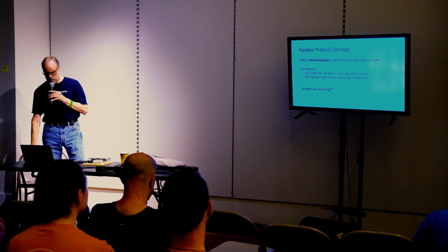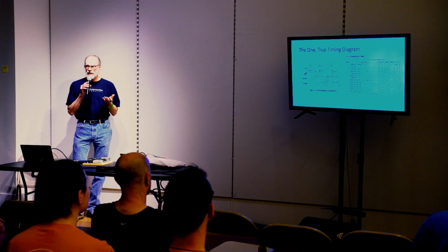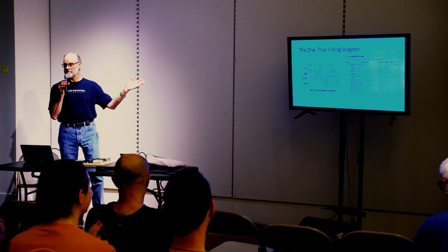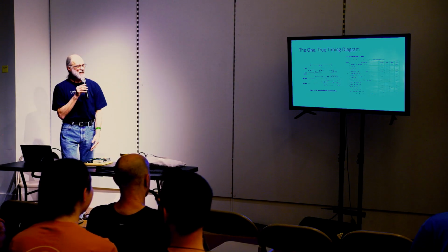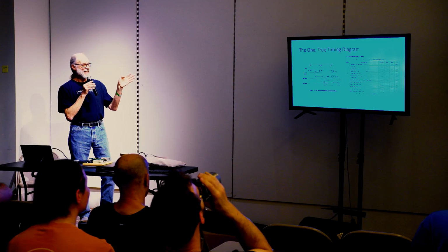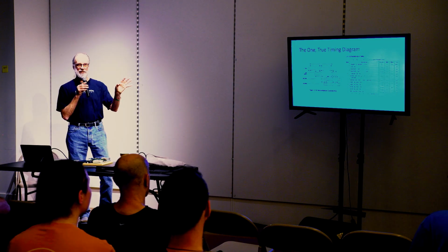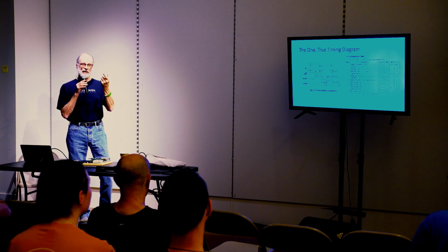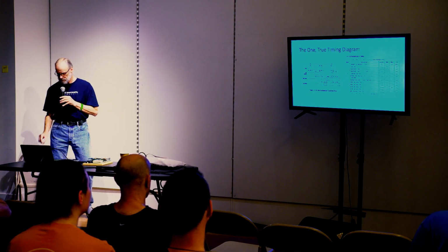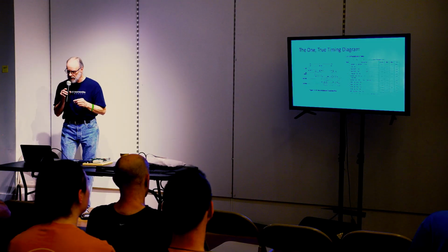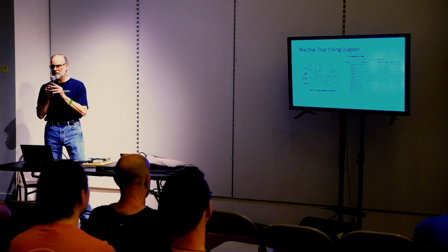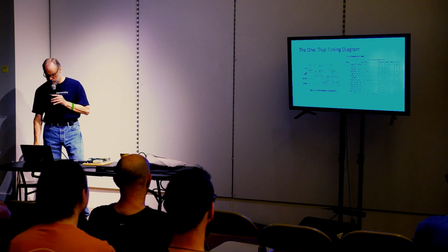So what are we timing? You guys are all pretty hardware, right? So I'm sure you've all, has anyone not seen a timing diagram? A couple people. One. Anyway, it's basically an API for silicon. It makes promises, it asks guarantees from you. If you meet the timing, everything is guaranteed to work and you're good to go. The important takeaway from here is that all the timing units in that far right column are measured in nanoseconds. There's just not a lot of time we're talking about.